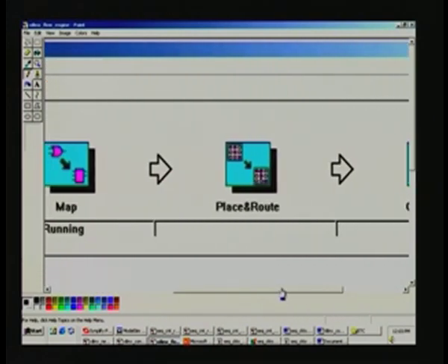And this is a laborious process, place and route. What we have done is selected the device, and then within the device it has placed all the primitive cells. Actual placing happens only here, and it places all the primitive cells at strategic points, considering what is best in terms of the frequency of operation that you may get. It always has an eye on the frequency of operation, and once it is placed, it starts the routing.